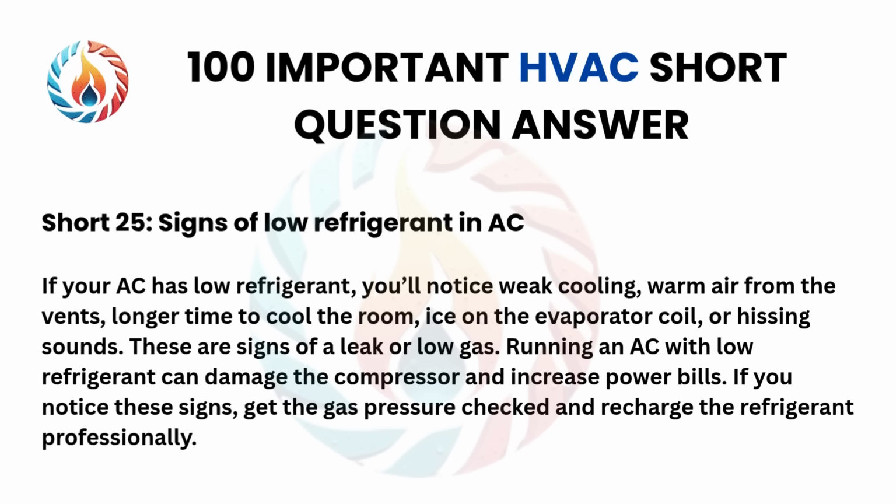These are signs of a leak or low gas. Running an AC with low refrigerant can damage the compressor and increase power bills. If you notice these signs, get the gas pressure checked and recharge the refrigerant professionally.